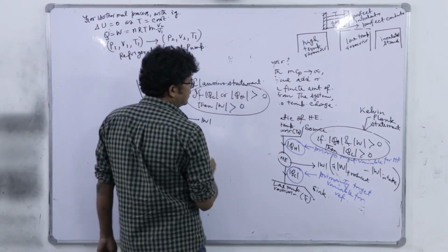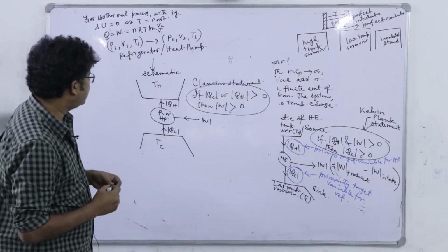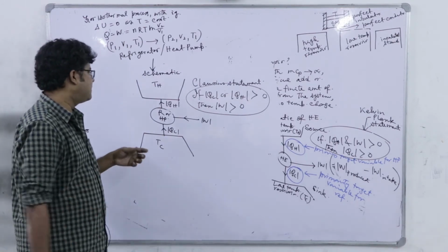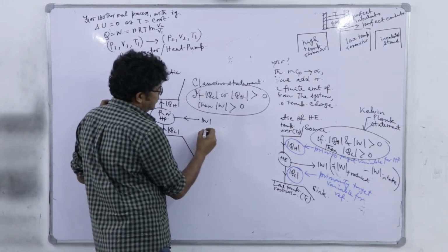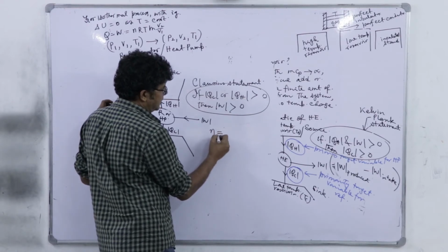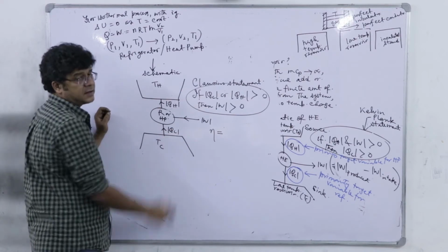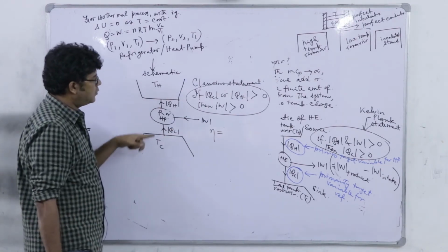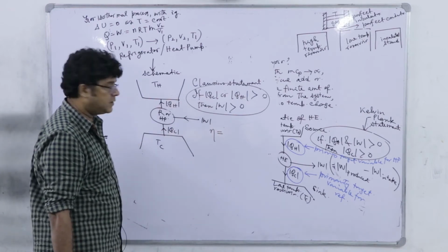So this is the Clausius statement basically, okay. So you see that here we can write efficiency equivalent term as my output divided by my input. What is the input? What is must be the input. And what is the output? For refrigerator the output is QC, for heat pump the output is QH.